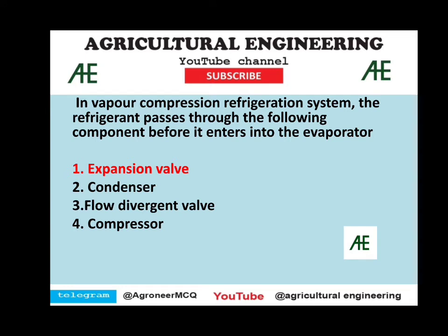In a vapor compression refrigeration system, the refrigerant passes through the following component before it enters the evaporator. The answer is expansion valve. So what I would like to suggest: study each and every part of the vapor compression refrigeration system, and just remember at which component the temperature of the refrigerant is high, or at which component the maximum amount of heat is removed, or maximum work needs to be done. There is a chance they will ask some question about this topic, so you just go through these topics.